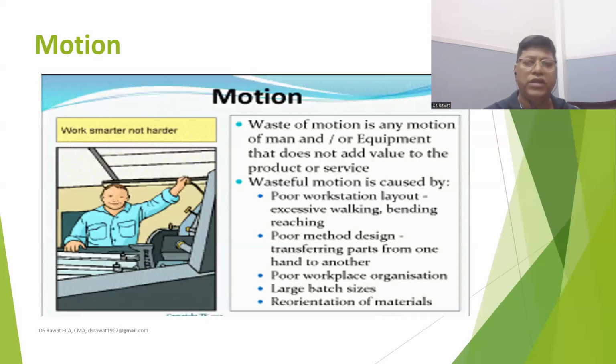If we stand side by side of a machine and see the performance of the machine, and we keep taking note of this, we will come to know what the performance of this machine is. Similarly, industrial engineers study the process, they study the motion, how the material is moving, what the movement of the workers is, etc. And based on that, they find the motions which are not suitable or which are not required, and cut those motions and improve the production.